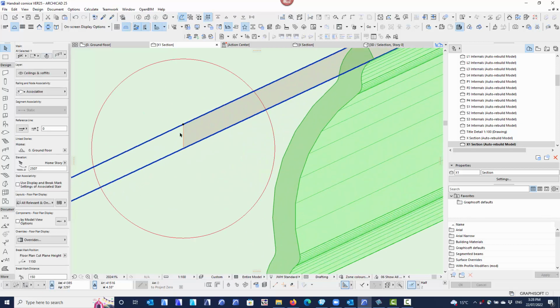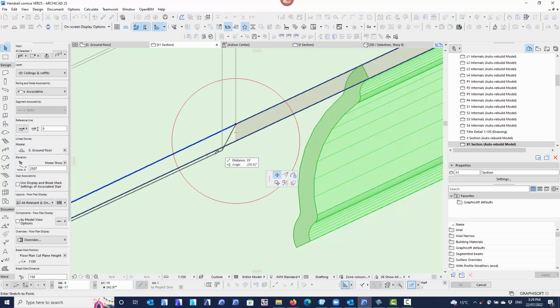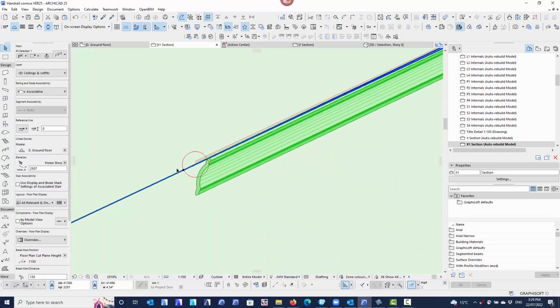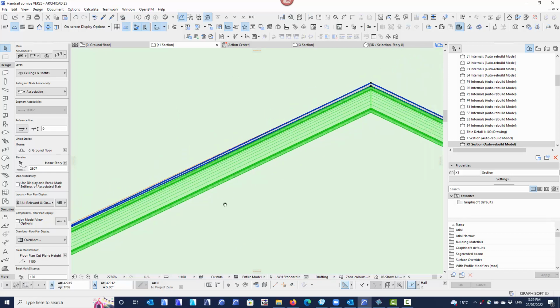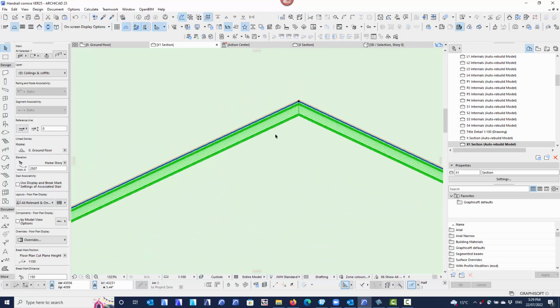Grab my cornice, and remember that that's the top. I need to drag it down to there, and then I need to drag it to here. So I'm going to try it all in one go and see what it does. And I need to drag that one from there to there, all in one go. And there you go, lo and behold. And the only other one I need to fix up now is make sure that I drag that node down, and all done.